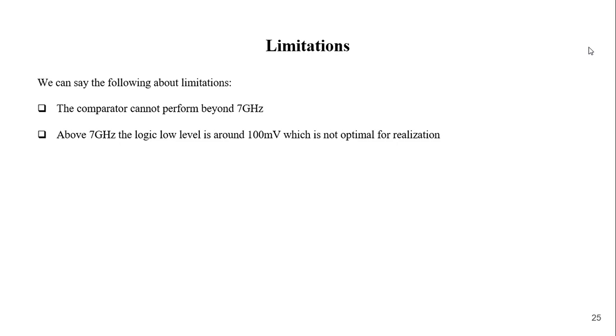The limitations of the comparator design is that it cannot perform beyond 7 gigahertz. And beyond 7 gigahertz, the low logic level is around 100 millivolt, which is not good for optimal realization.